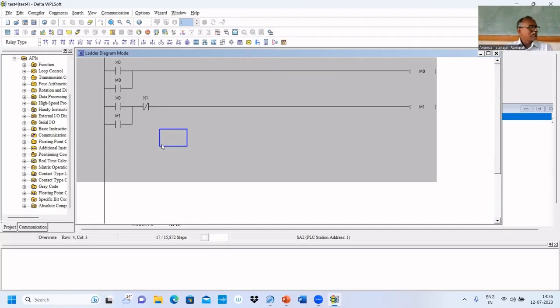So we have to use a timer. If you put M0 and M1, what will happen? Now we will put this way. I think now these two statements you understand. First, if you use M0, we can turn on, but you cannot turn off. In the second statement, we can both turn on and off, but immediately it will be turned off.